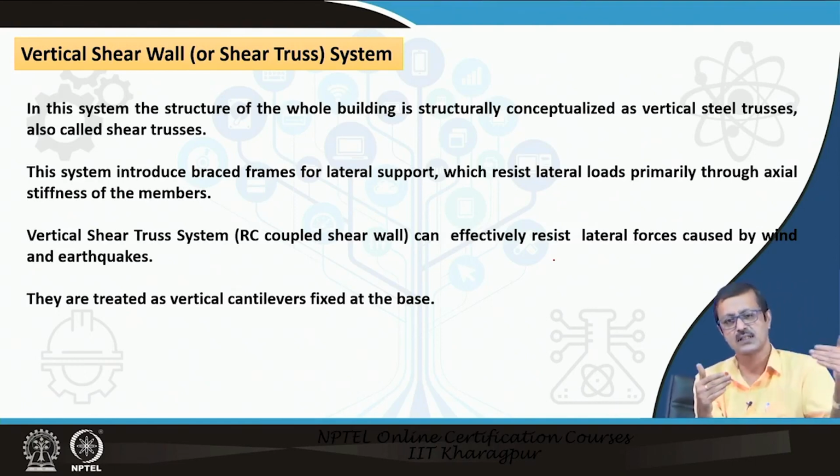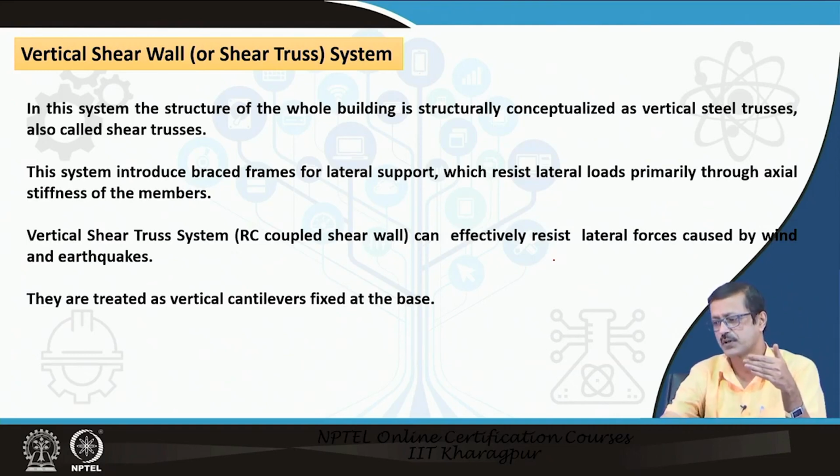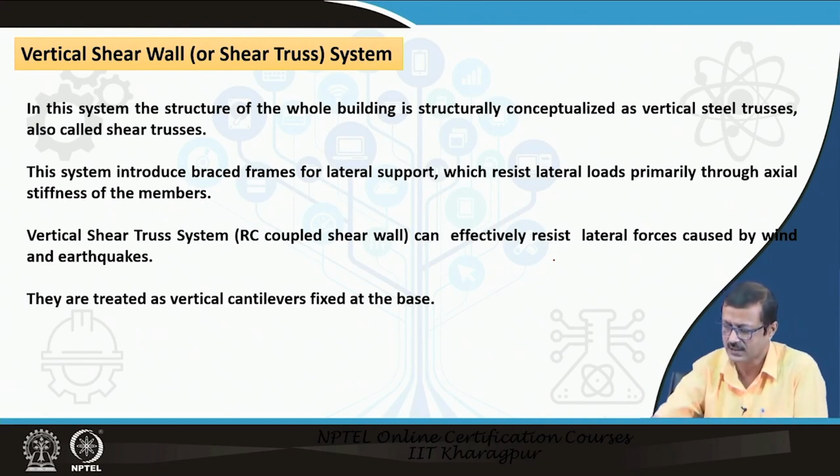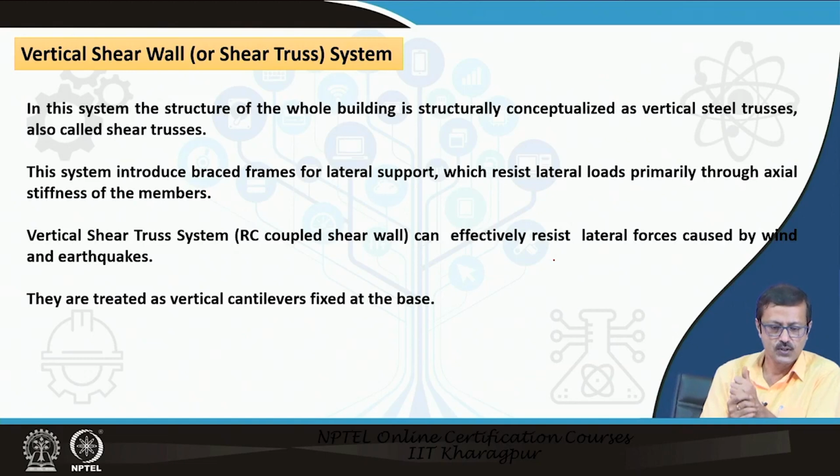Why shear? Because if you see, the lateral load comes to the building at a particular height, it creates a kind of huge shear at the base. It's a cantilever kind of a thing. And it is going to resist that, primarily the wind or earthquake generated lateral load. This building system is actually treated as a cantilever fixed at its base, as I have told you.